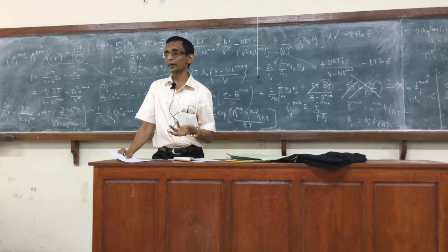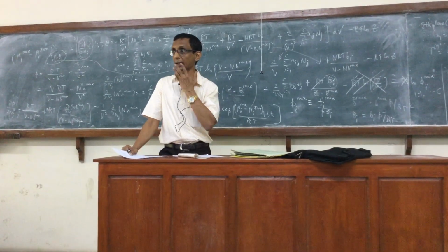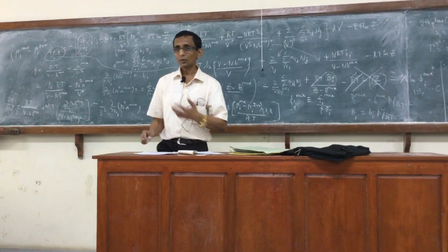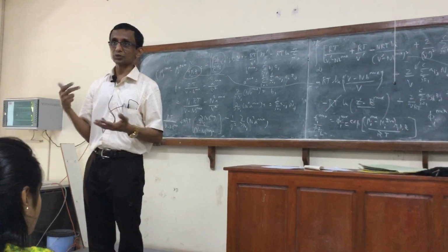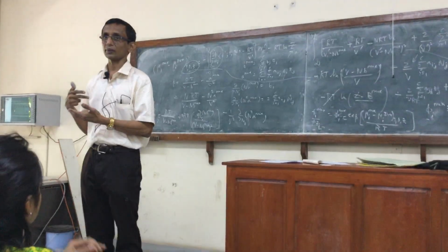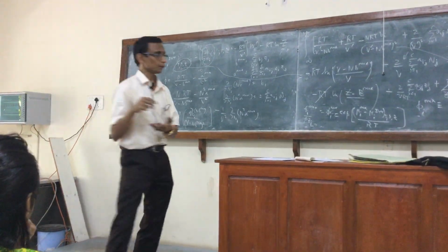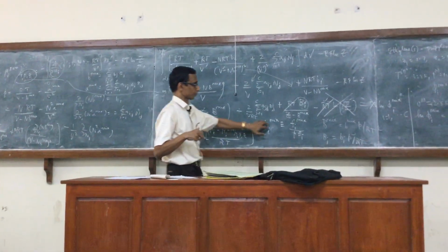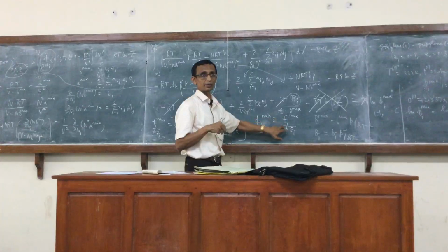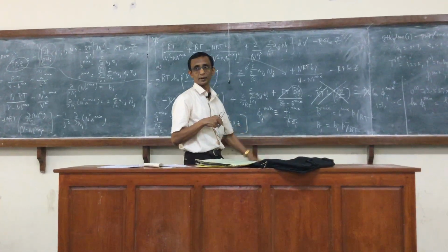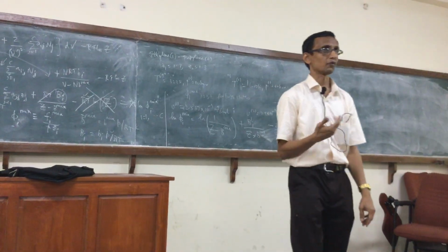So this will give another indication, because the capital Z gives an indication of the deviation of the actual mixture from the ideal gas mixture. If Z is equal to 1, then you get the ideal gas mixture. In the same way, for the ideal gas mixture, f_i is equal to P times z_i, and so the fugacity coefficient will become 1 for each of the components.